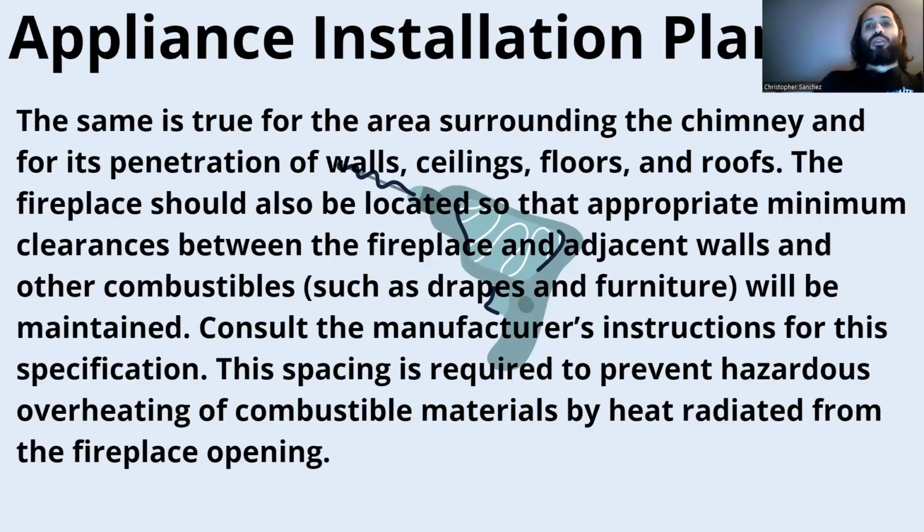The same is true for the area surrounding the chimney and for its penetration of walls, ceilings, floors, and roofs. The fireplace should also be located so that the appropriate minimum clearances between the fireplace and adjacent walls and other combustibles such as drapes and furniture will be maintained. Consult the manufacturer's instructions for the specification. This spacing is required to prevent hazardous overheating of combustible materials by heat radiated from the fireplace opening.